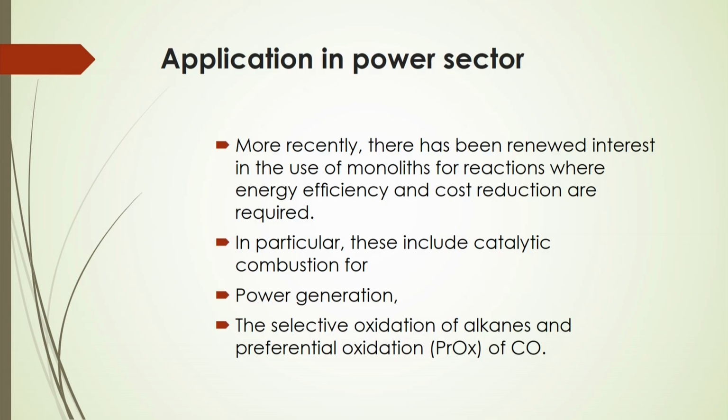Earlier, in the conventional way, only in slurry reactors, the gas, liquid, and solids were moving inside the bed arbitrarily, that means with internal circulation of the fluid medium to get good mixing there. But sometimes that back mixing may hinder the reaction performance.